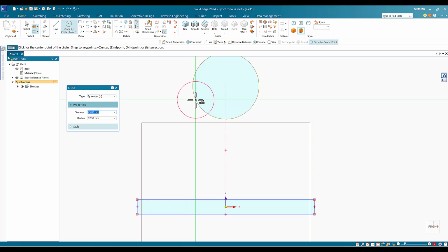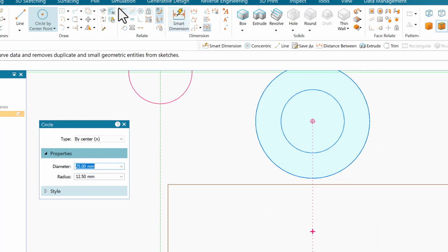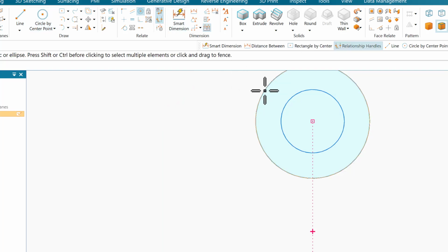Highlight the bigger circle, the 45, and then this reveals the center. When you see concentric, I'm gonna click. Okay, just to make sure they are concentric together, so I'm gonna use the relationship concentric. Click on concentric. I say, okay, I need this inside circle to be concentric with the outside circle. Did you notice something here? It gave you the concentric relationship here.